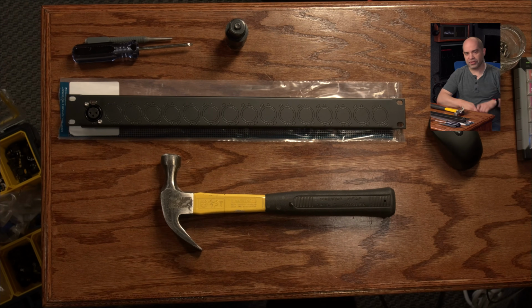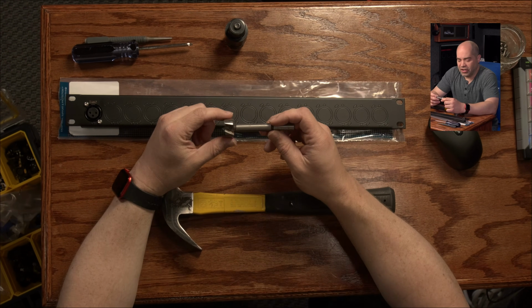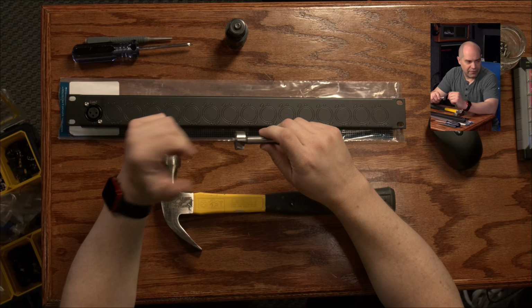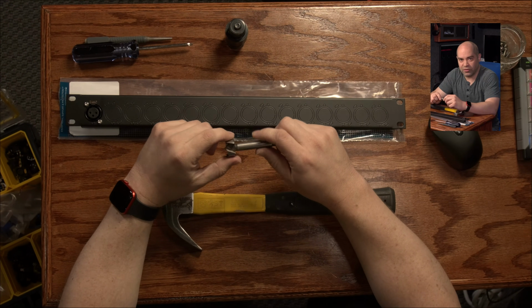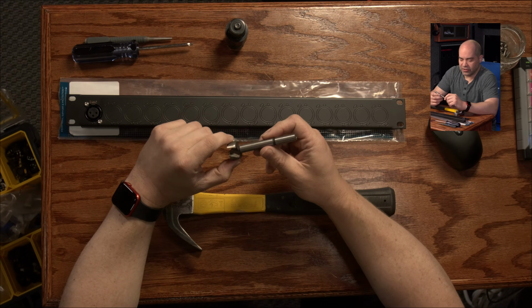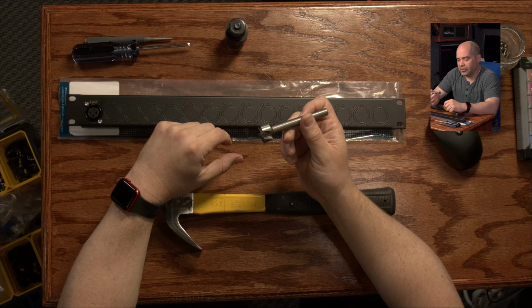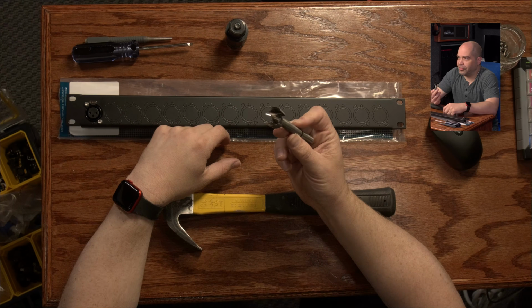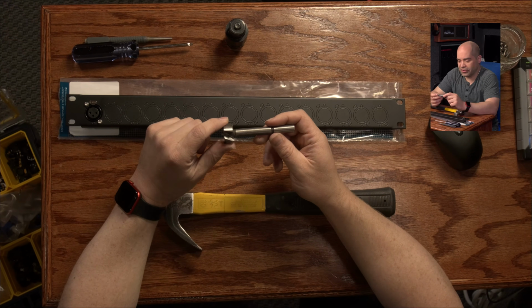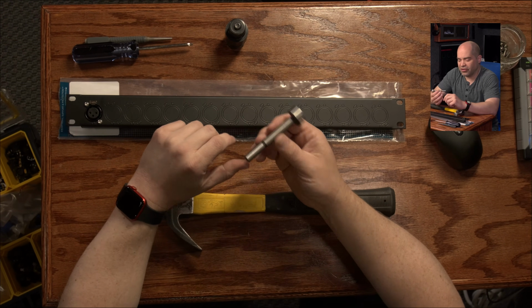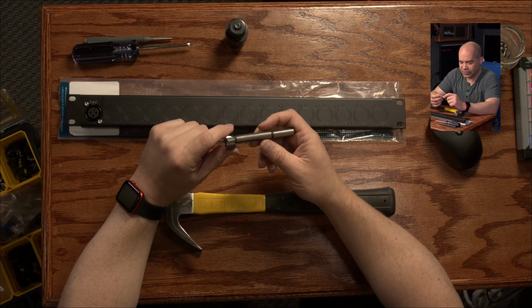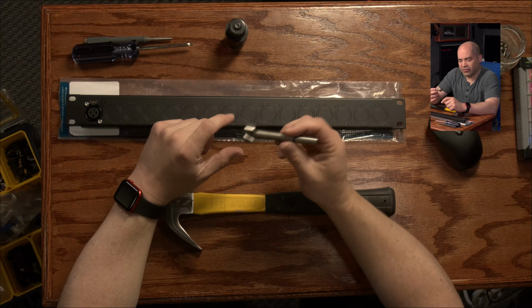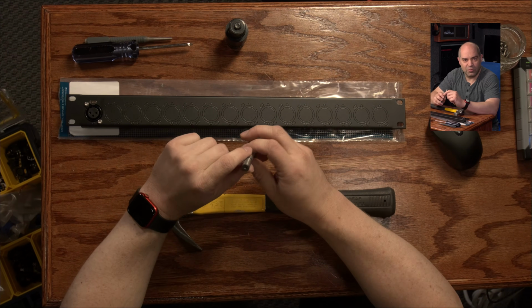If you ever need to go into wood, I don't do that a lot, but every once in a while I have a handful of these connectors directly in the wall where I only need one, and I don't want to deal with the wall plate. So in that case, I like to use a Forstner bit. So this is a Forstner bit. It's exactly 15/16 inch. These are a little bit hard to find. I don't remember where I found this one. I've had this for a long time too. But yeah, that allows me to cut the exact right size hole in wood.